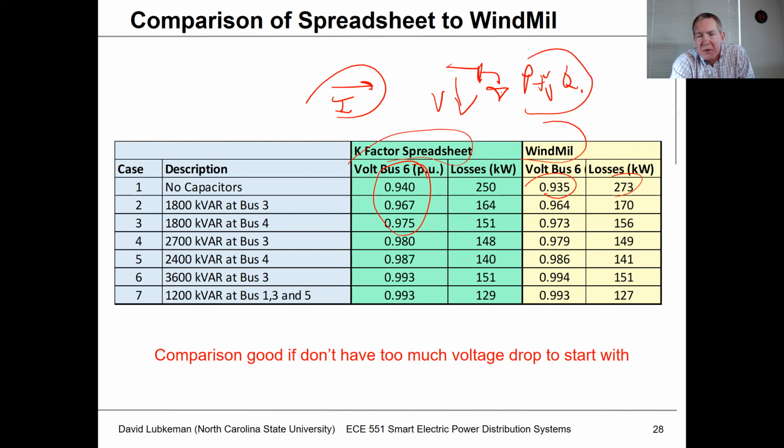So with this constant power load model that we use a lot of times, if voltage drops, current goes even higher, which causes even more voltage drop, which causes the current to adjust a little bit higher as well. And because of this, typically for really large voltage deviations, we don't get the same amount of accuracy.